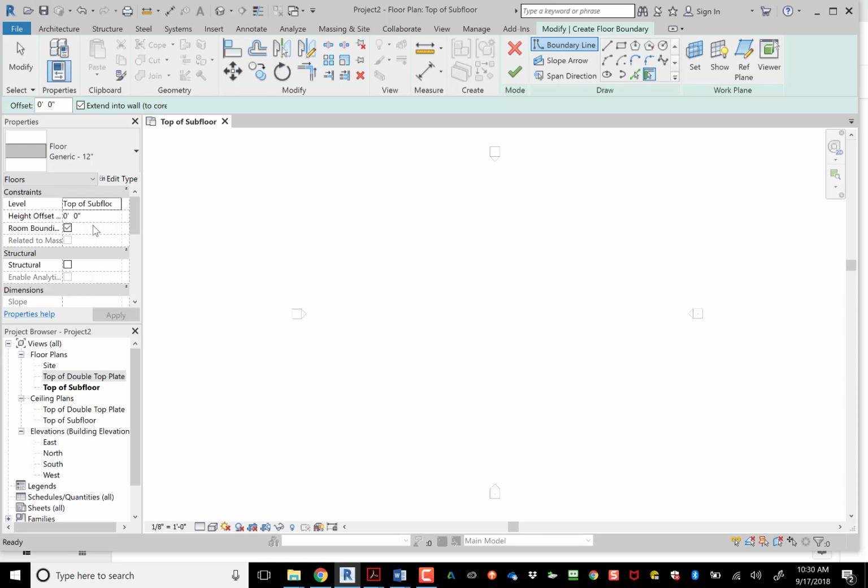There's also the option of changing it first and doing it properly, but I'm just gonna go ahead and draw it with this 12-inch floor, which is way too much. So remember in Revit, you would have your pier block maybe here. You want to kind of align it to your pier block. Let me just throw it in here. Oh, it's way too big. Okay, I'm just going to put it down whatever size it comes in.